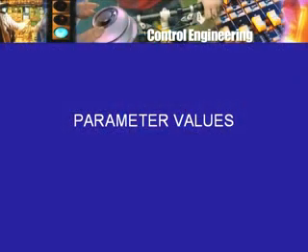Then what is going to happen to the speed? Assuming the load torque is constant at the old value and the supply voltage Ea is constant at the old value. So this is a change in parameter value, or alternately uncertainty: Kb was assumed to be this much, but there was a mistake in the measurement, so it is not really that, but something else. What would be the values of speed and armature current that would result in the steady state?